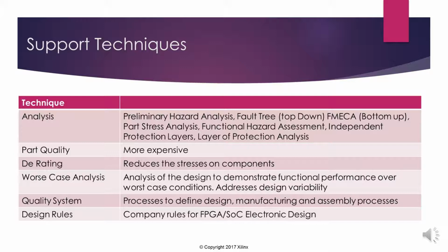Now we may even do, if we have two boards, it may be that we simulate one board at its maximum worst case and the other one at its minimum worst case, to ensure that when they're biased like that, they still actually communicate and talk to each other reliably, and we don't introduce any problems that way.